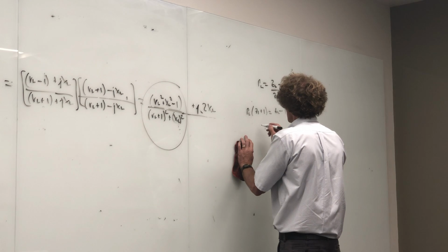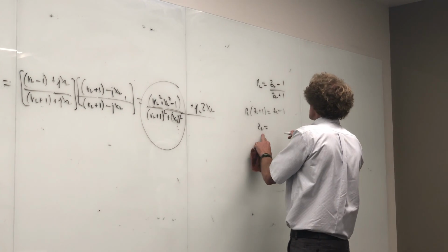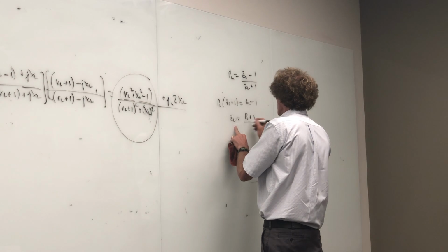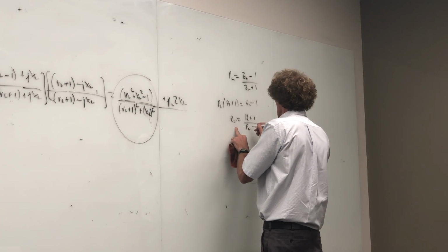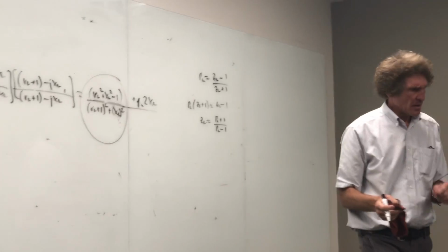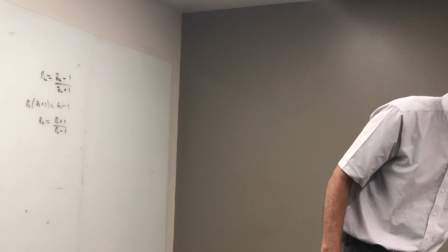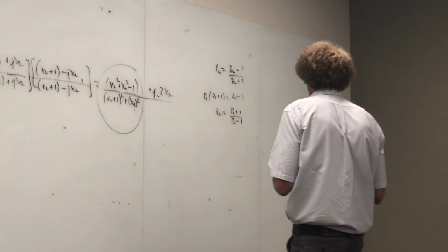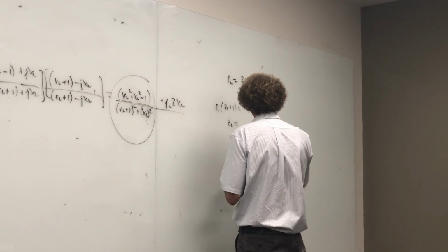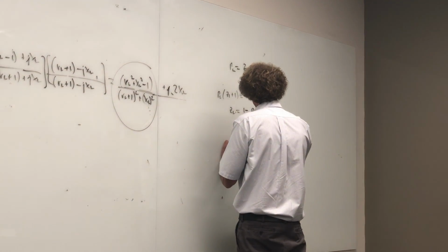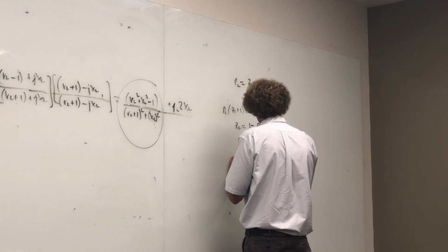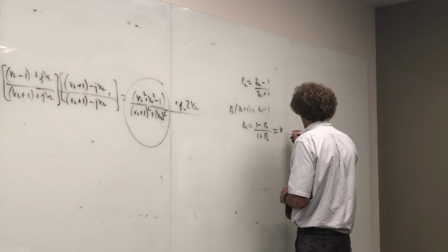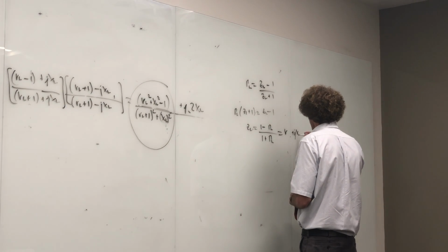All right, that would be ZL is equal to (1 + gamma L) over (gamma L - 1), and you should have that. Oh, I'm sorry, 1 minus, my bad. There's a minus sign there, so it's (1 - gamma L) over (1 + gamma L) here. And that's equal to the real part plus j imaginary part of the load.